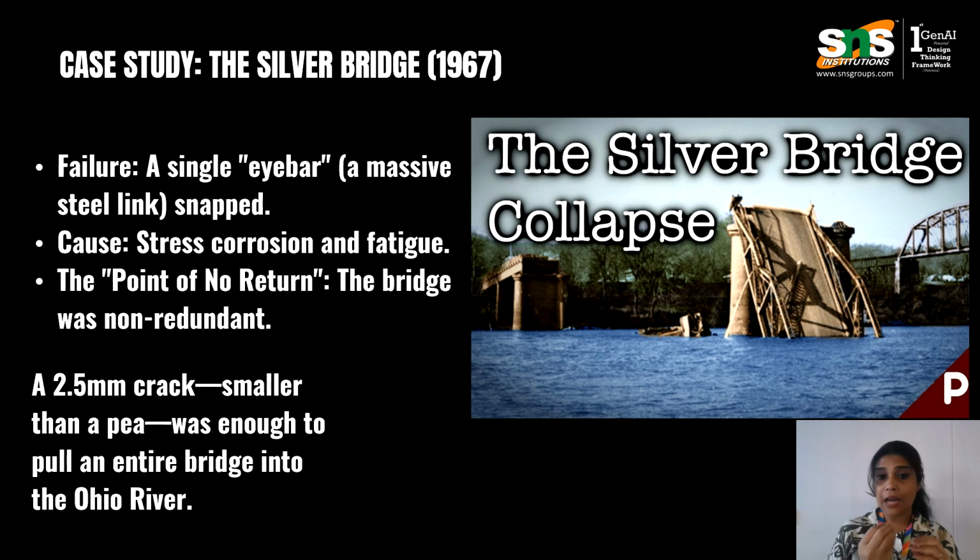An eye-bar, a massive steel link in the bridge chain. It had only a very tiny crack, just about 2.5 mm deep, but that crack kept growing due to corrosion and fatigue.